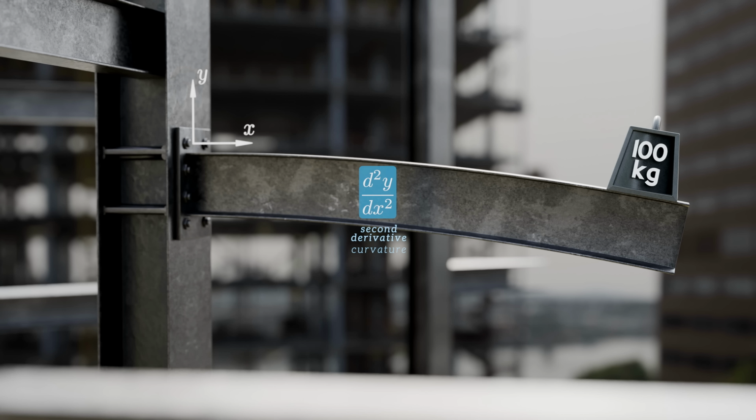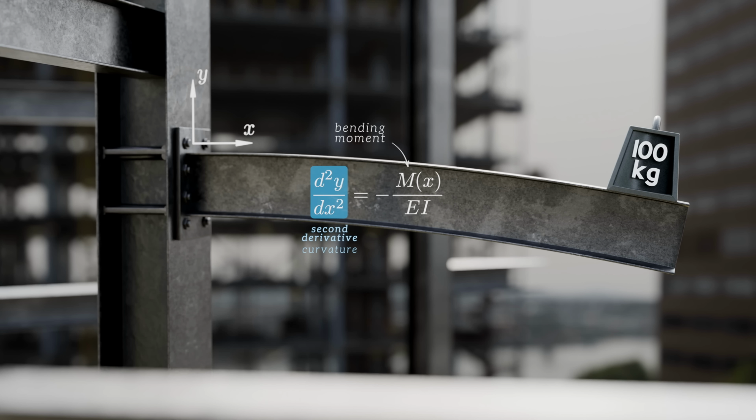At any point along the beam, this curvature depends on the bending moment at that location, produced by the applied load, and on two parameters that describe the beam's stiffness: the Young's modulus E, a measure of the material's stiffness, and the second moment of area, I, which reflects how the beam's cross-section resists bending. Mechanical and civil engineers use this differential equation all the time to design and analyze structures.